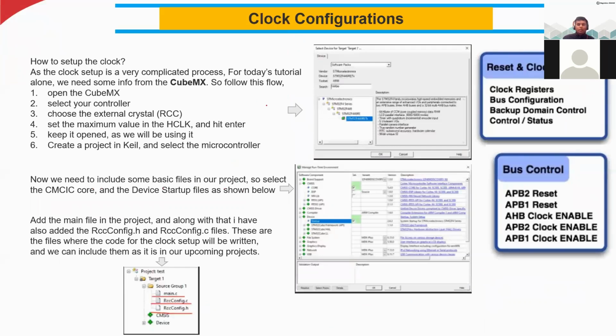So how to set up the clock? Of course, you have to set up the clock for each project. The clock setup is a very complicated process. For today's lecture or tutorial, we just need some information from CubeMX. In case you use CubeMX or Cube IDE, that doesn't matter. It is the same. You have to open the tool, select your microcontroller and the board, and then choose the external crystal. That is the crystal clock.